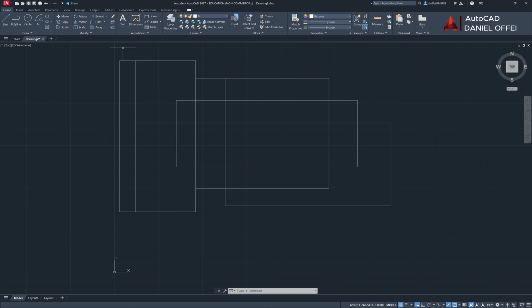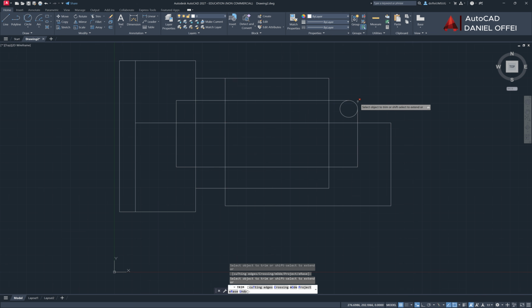Before we look at the fillet tool, let's look at how we can also use the tan radius to get the same effect. So I go to my tan radius circle option. I select my first line, select the second line, then enter the radius of the fillet. Then I can trim the parts of the lines that I don't need. Then I have the fillet that I want.